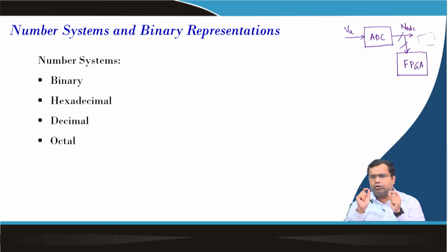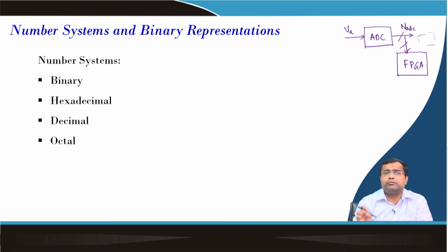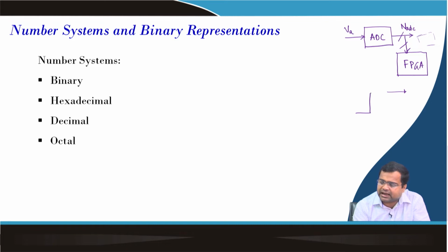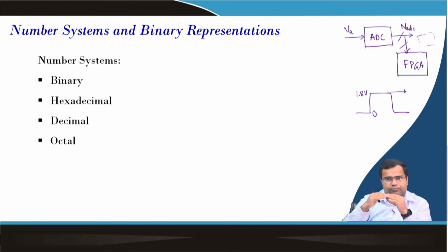So, you can, though there will be a delay of course, but still this delay will be much smaller than an actual serial ADC. So, in summary, whatever ADC you take, whether it is serial or parallel, these lines are basically a number, and depending upon the logic level, because now we are talking about CMOS logic, which can be 1.8 volt logic, earlier it used to be 3.3, 2.5. So, it will only generate either high or low. When it is high, if the logic level is 1.8 volt, it will be 1.8 volt or it will be 0 volt. So, each wire will carry a voltage, which we can take as value 0 or 1, which corresponds to a certain voltage.